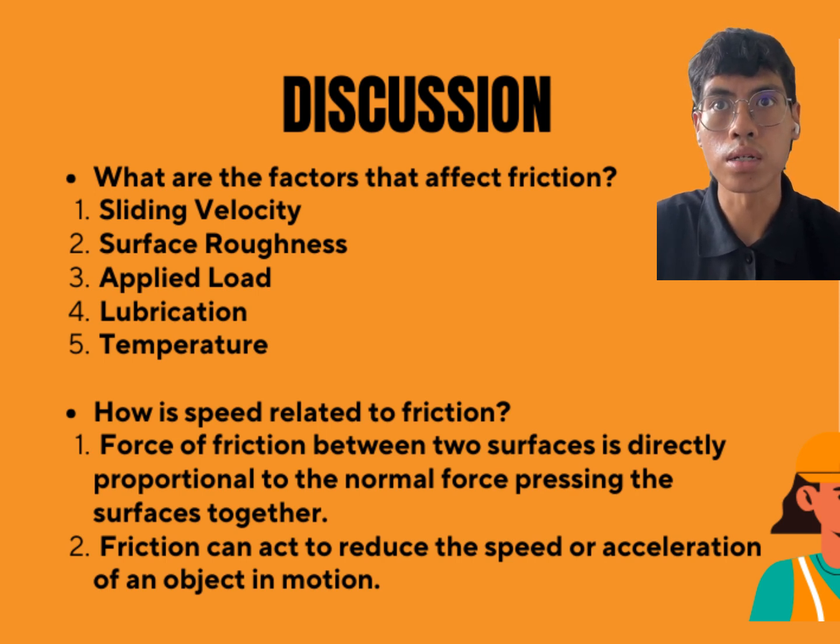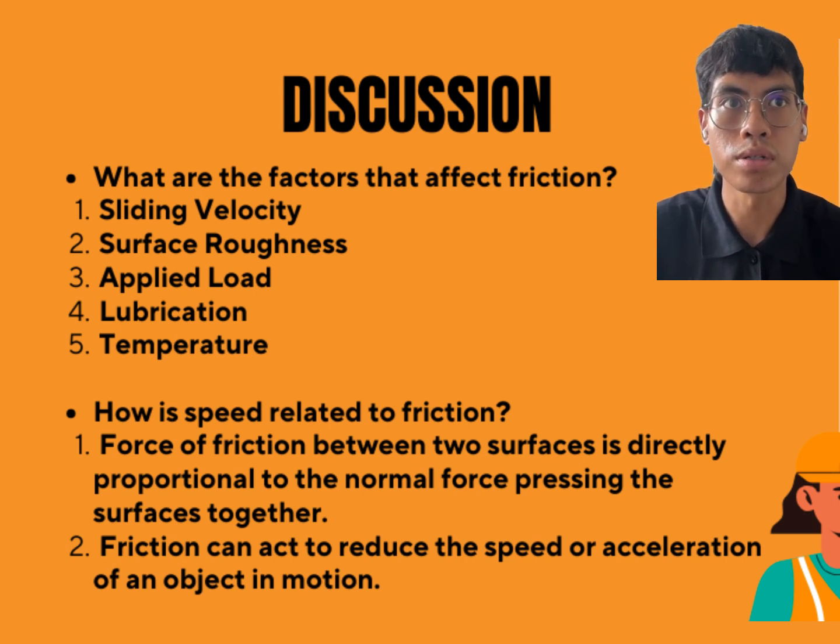And the third one is applied load. It conforms to the first law of friction, where the friction is directly proportional to the load given. So when the load is increased, the friction value of the materials also steadily increases. And the others, number 4, lubrication, and the 5th one is temperature.